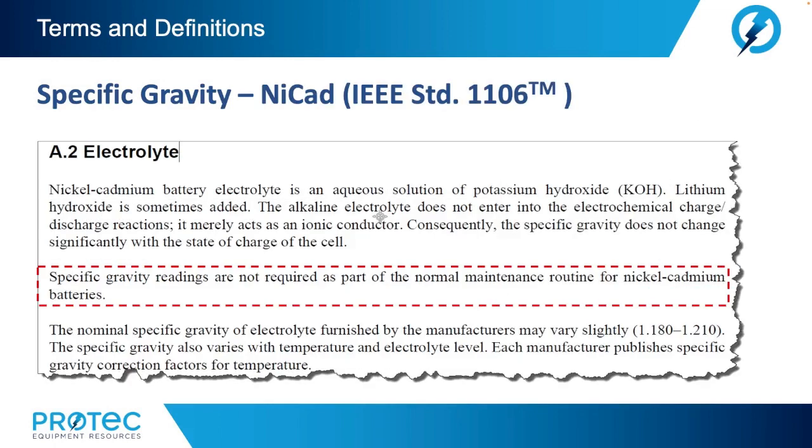Now, specific gravity readings are not required as part of a normal maintenance routine for nickel-cadmium batteries, as we see referenced in the IEEE standard 1106.